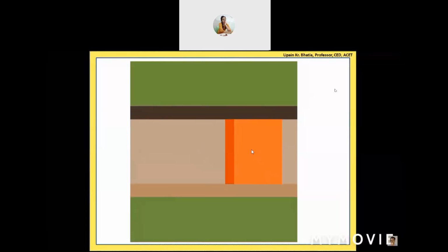And to join these two levels, we have provided an inclined ramp, so it is not depressed all of a sudden. From here, it is the canal bed. From here, it starts gradually going downward up to this level, and we maintain a horizontal depressed floor up to this. This is basically done in concrete to secure this depression of the bed and this ramp also. We provide everything in concrete. A concrete floor is provided in this station.